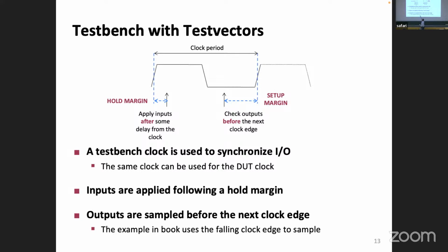The real problem is you will have a hold time violation against this flip-flop here, against this state here. So this is actually why we are leaving some additional time. I don't want to get too much into it. I don't want to involve setup and hold times in the test bench as well. Let's just agree that we leave some separation between them. And the way we are going to do it in the test bench is going to be slightly entertaining. That's why I'm talking about it so long.